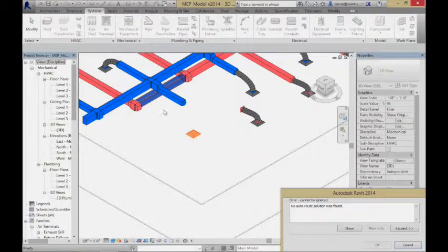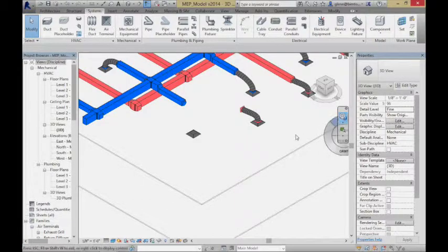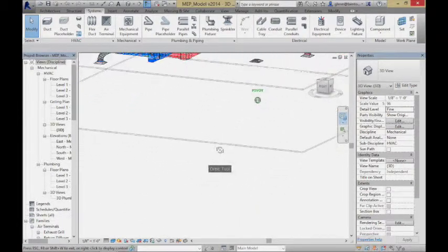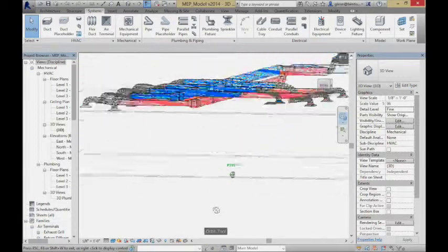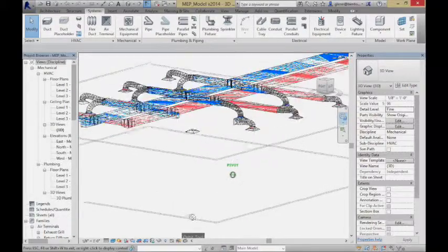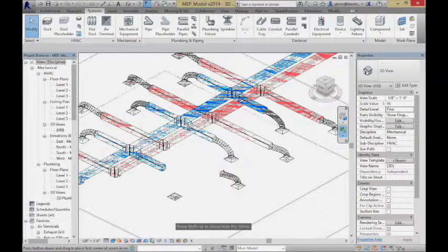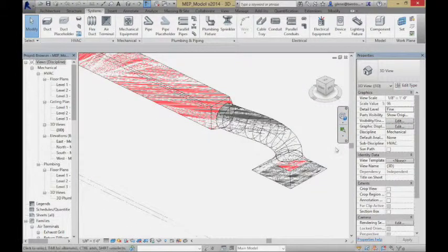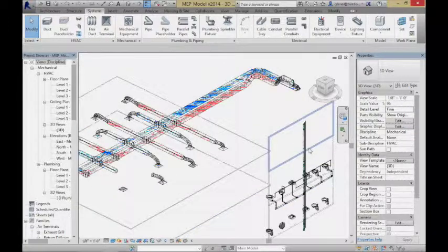In this case it's saying it can't find an auto route solution. Let's talk about why that is, because it's that same sort of issue of the difficulty of making the physics work. In this case, you'll see what some of the problem is. If I'm trying to run the system with a series of hard ducts, the problem is it may have trouble connecting all the elbows and pieces together to actually make a firmly ducted connection between those different things.